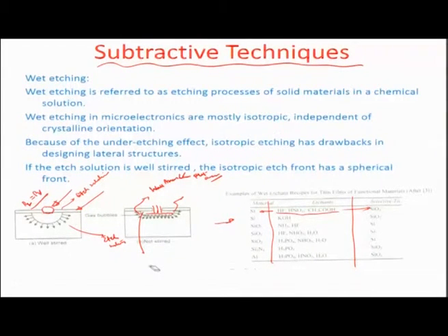which produces an undercut. So, an undercut typically would happen because of lateral etching. If materials are removed properly, then undercut probably happens in a homogeneous manner, but if it is not removed properly, then undercut happens in a very skewed manner, and obviously whatever size or domain you are etching, the overall etch profile that will eventually come out will be higher in width than the planned etching zone.